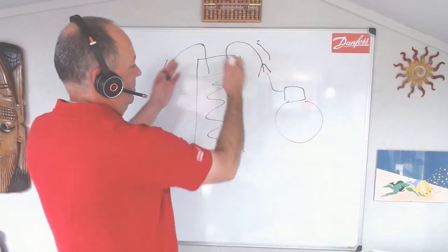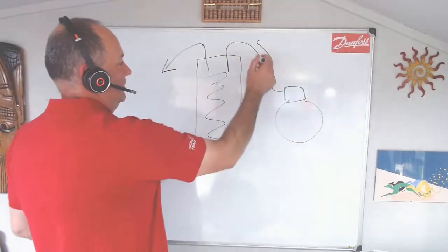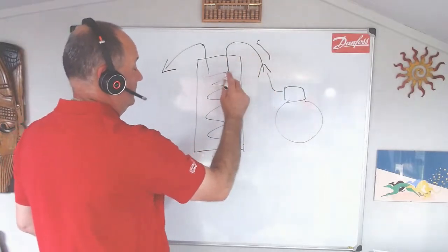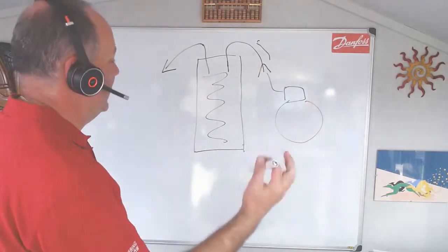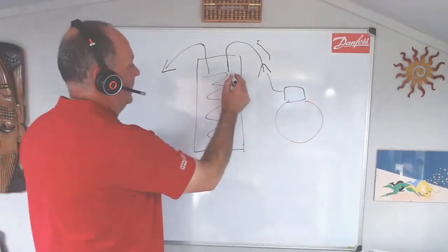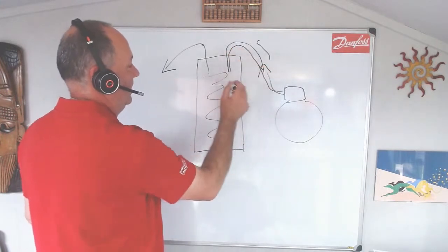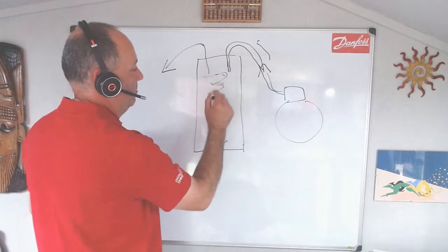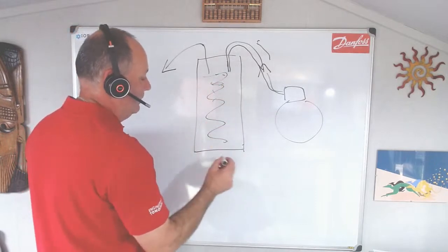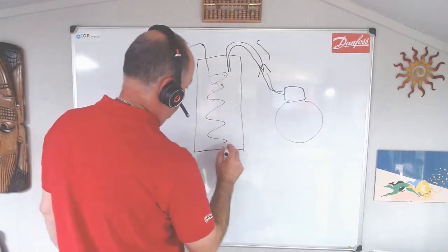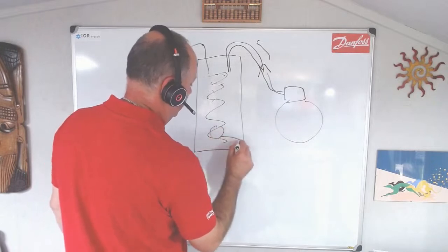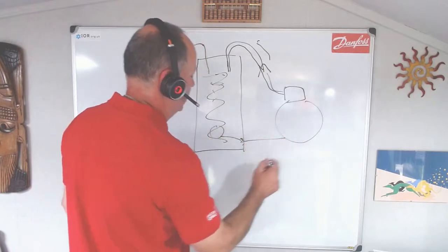it comes into a space where the speed is actually slowed down, and the oil that's entrained in the hot vapor that's coming in here basically gets caught on the mesh, and it drips down, and then you can have a float at the bottom which opens an orifice which then feeds back to the crankcase.